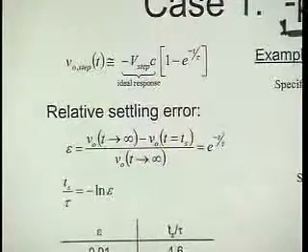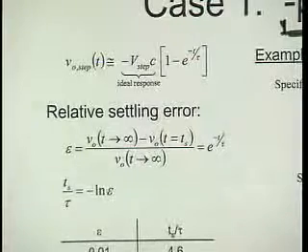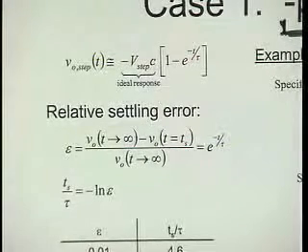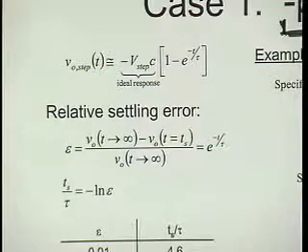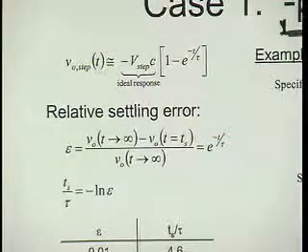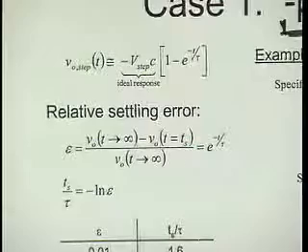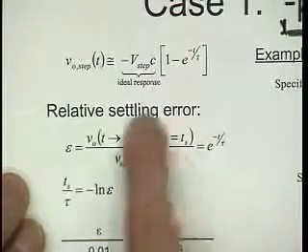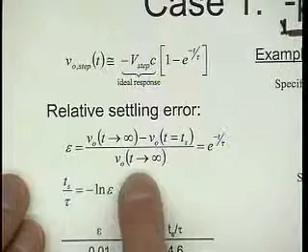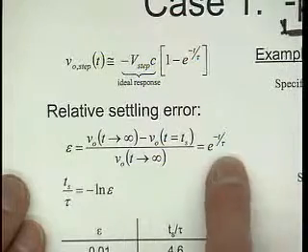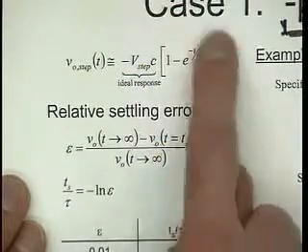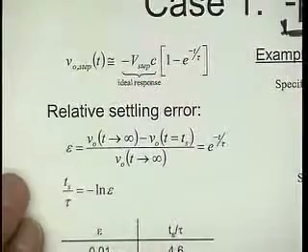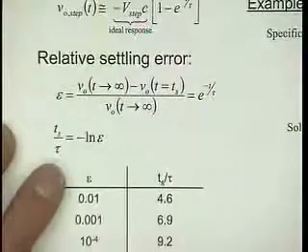If you have an A to D converter that goes at 100 megasamples per second, then a period is going to be 10 nanoseconds long. Most of the time, our amplifier has only half a period to settle, so in 5 nanoseconds it will have. So then this TS would be 5 nanoseconds, and we divide again by the ideal value, and then this just comes to this error here. So that's the relative error.